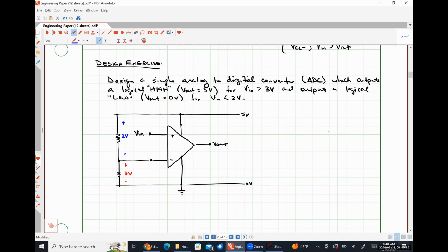So effectively, the sweet spot for op-amp biasing is kilo-ohm size resistors because they're about 1,000 times smaller than the internal input resistance, and they're about 1,000 times larger than the internal output resistance, so that as long as we're biasing with kilo-ohm size resistors, 95% of the time, everything's going to work out fine, and we don't need to really pay any attention to things beyond that, okay?